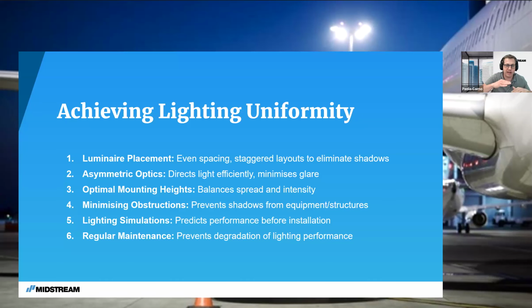So basically, every luminaire distribution will add on top of each other until we reach the lux level, but the uniformity is given by the shape of the distribution. This means that if you lose a luminaire, for example, you're not going to have a decrease in uniformity.